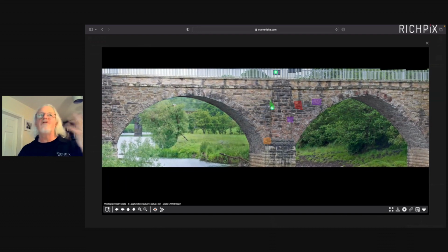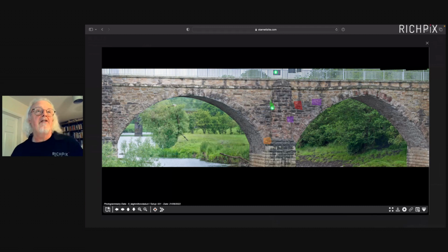And also, I wouldn't say I wouldn't use a LiDAR or a drone, because I may well need to. But this took about 5 minutes to do, less on site. All I did was just mount a camera. This is a Sony A7R. So it's around about 4 or 5 kilos worth of camera and glass on a tripod, and just swing around with an overlap, around about a 25% overlap, and then stitch them all together.